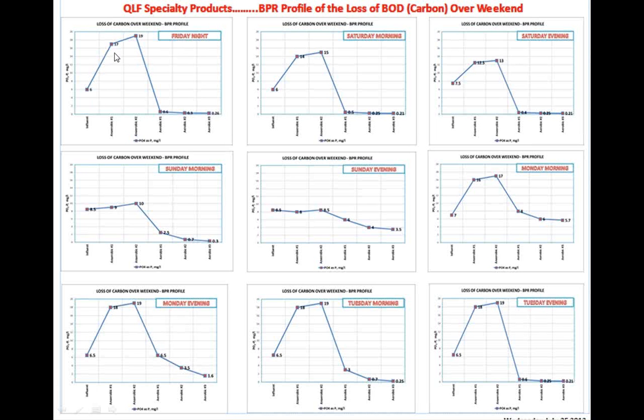Healthy release is anywhere from 2 to 3 times and more from the influent. So let's say the influent is 10. You'd want to see this at 20 or 30 for it to be healthy. In this case, I believe it's 6 there, so you'd want it to be 12 to 18. So this is a good release. And then right in the first zone with plenty of oxygen, it brings that orthophosphate level right back down to almost nothing, and it stays there through the rest of the system.